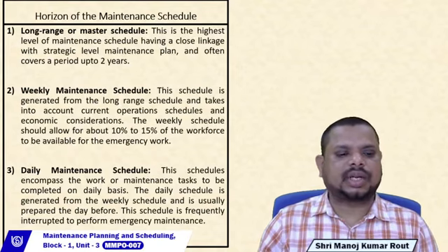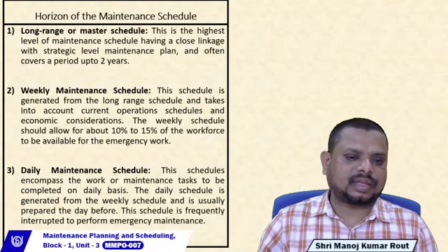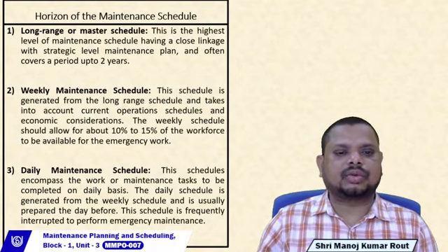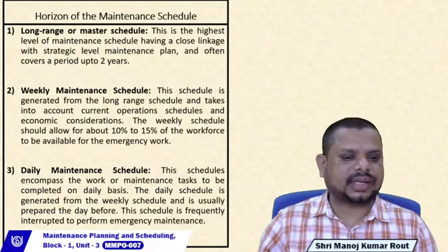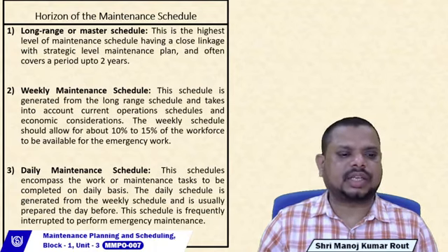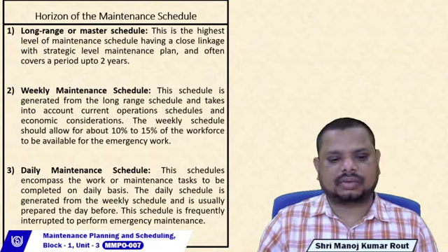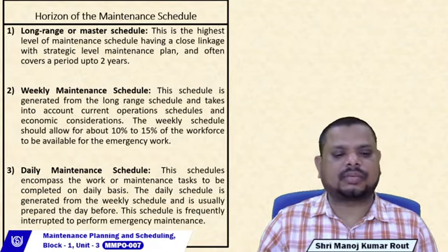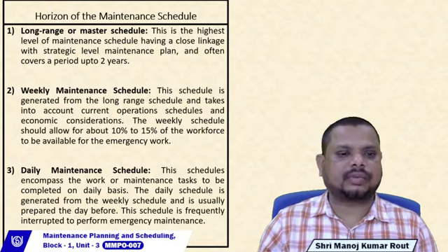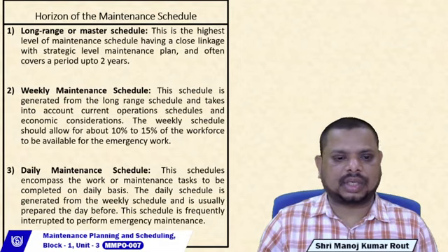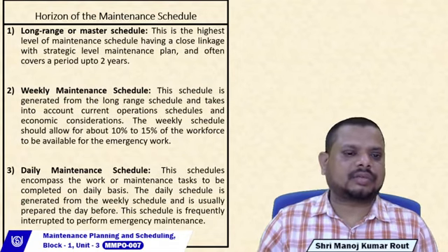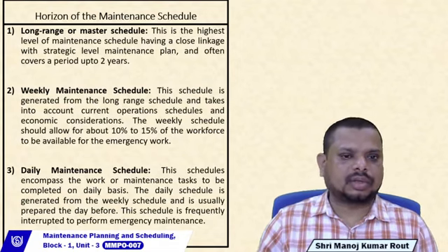The daily schedule is generated from the weekly schedule and is usually prepared the day before. It is done by the maintenance managers to provide the daily maintenance schedule to the maintenance technicians and various machine operators, so that they can easily perform the daily maintenance. This schedule is frequently interrupted by the performance of emergency maintenance. By providing daily maintenance, you can easily avoid a large amount of breakdowns and eliminate a large amount of downtime.